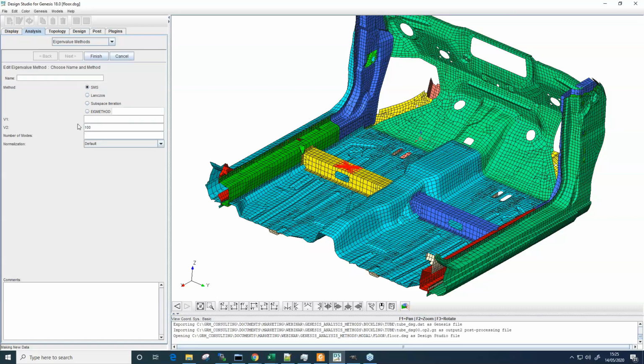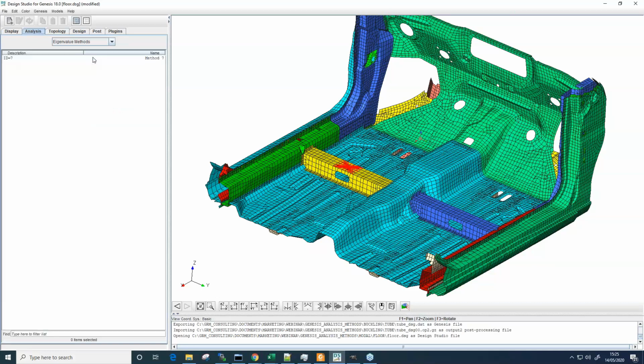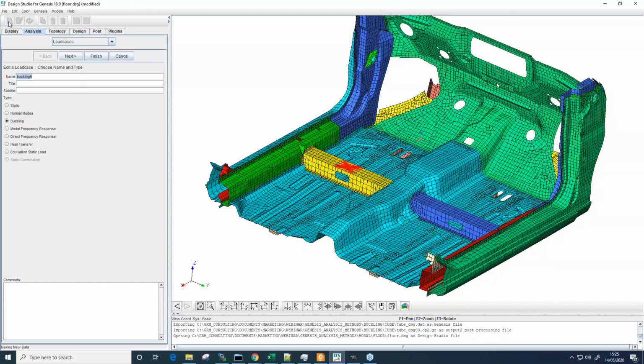You don't need to define how many modes are requested, so in this case I won't. In my slide I said I would, but I won't. It's basically the maximum number of modes to recover, so if there are less than 100, there's no problem. It's sometimes useful to do that if you're concerned about creating a really large output file and you don't care about so many modes.